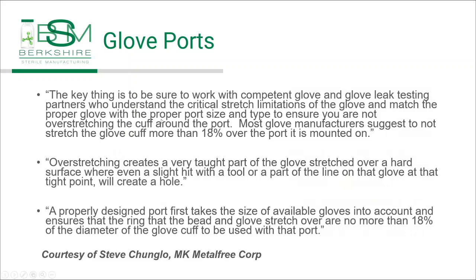With one of our isolators that we brought in, we had a problem that we were occasionally getting glove holes in the collar up around the shoulder area of the operators after operation. And we did a lot of work and a lot of investigation and found out that it was really due to the glove and glove port not being matched correctly to one another.